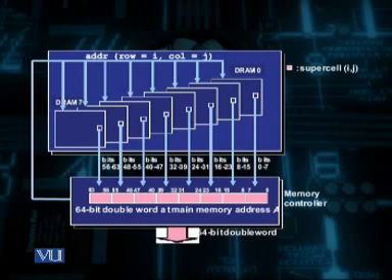These 8 megabyte modules can be connected as shown over here in this diagram by applying a module select signal, which is usually the upper address part of the memory address line, which selects a particular block or a particular module within this bigger 64 megabyte memory.